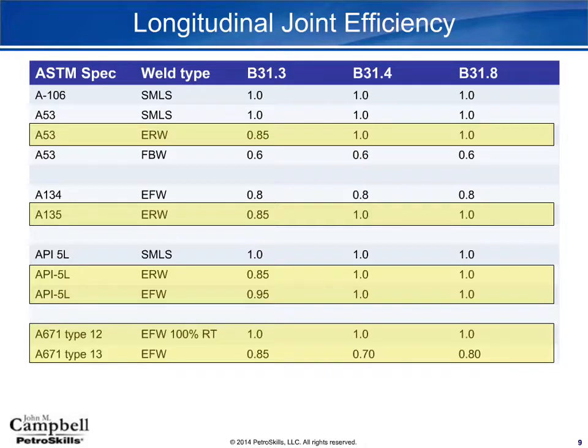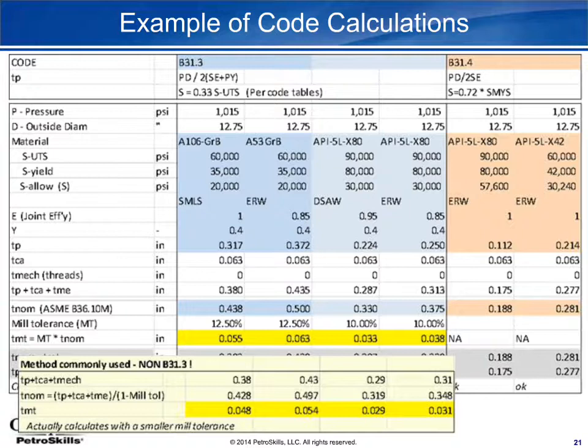let me push that out, hang on a sec. This slide right here, you can see that in B31.3 we had to use 0.5 wall thickness pipe versus 0.38 for seamless. The first two columns there are seamless and ERW, and for B31.3, that's affecting wall thickness.